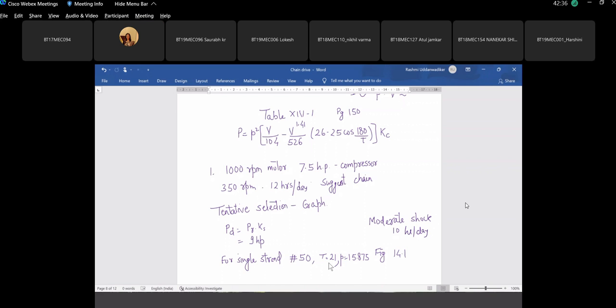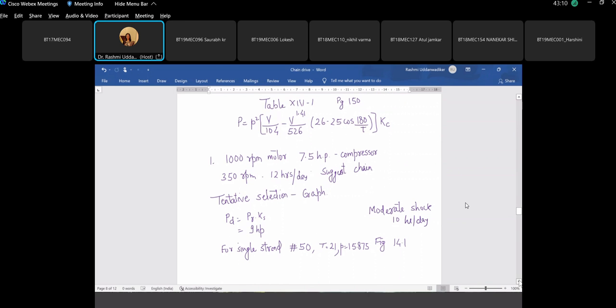Now the first check here is the kind of pitch that you are selecting. We have to check what is the diameter of the bore. We are selecting the sprocket, and the sprocket will be mounted on the shaft. So the bore is the hole which is cut in the sprocket for this shaft. Check what is the diameter. For pitch less than 25.4, in the previous page or in the table 43, it says that the maximum permissible diameter of the bore would be less than number of teeth minus 5 into pitch by 4, if the pitch length is less than 25.4.